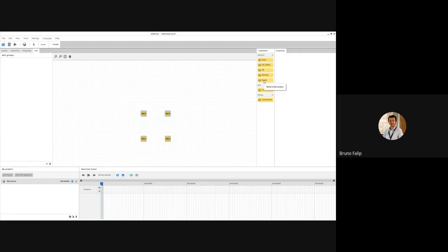There are DALI 2. The only thing we're not doing with DALI 2 at the moment is the, I forgot my word. Oh yeah, I know. It's the multi-master. We use a single master possibility control at the moment, when DALI 2 allows you to use multi-master, but we're not multi-master compatible at the moment.